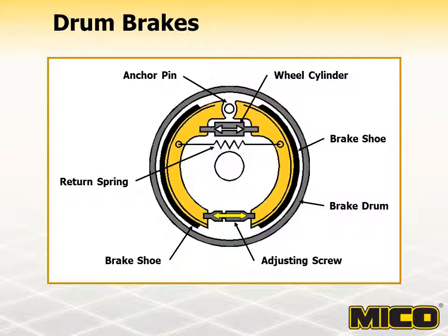There are a number of drawbacks to drum brakes. They are more sensitive to changes in the coefficient of friction in the brake shoes. Drum brakes are prone to brake fade. This is where braking torque builds to a point and then seems to drop off, requiring increased pedal force. Because drum brakes are enclosed, they do not dissipate heat easily. Also, as the linings wear, there is no exit for the lining dust or other contaminants, so they build up inside the drum. Drum brakes are self-energizing and often duo-servo.